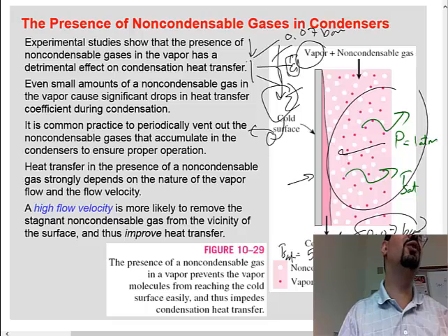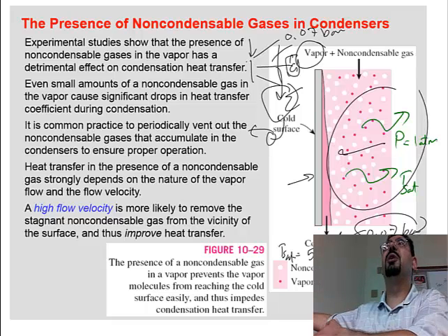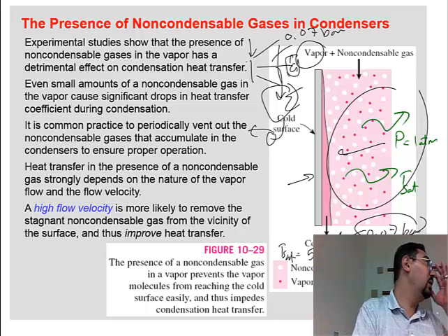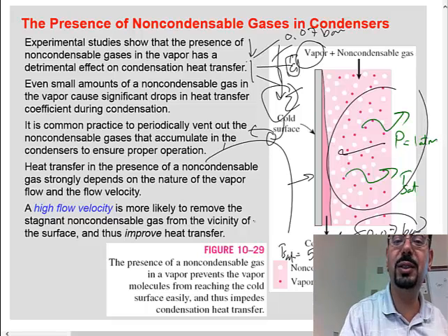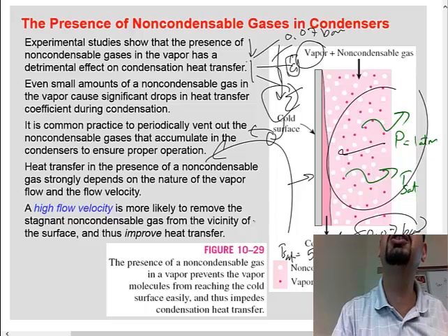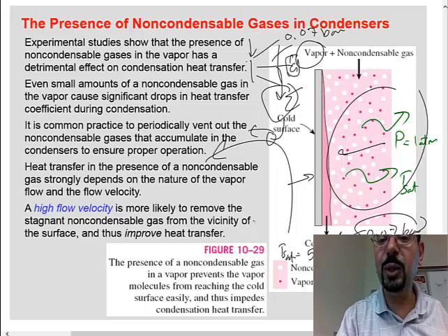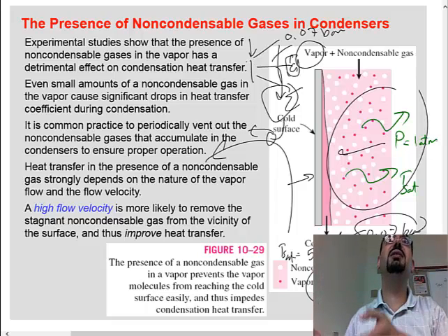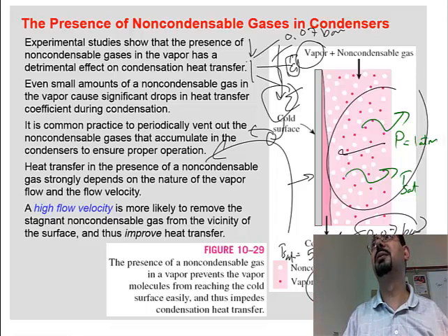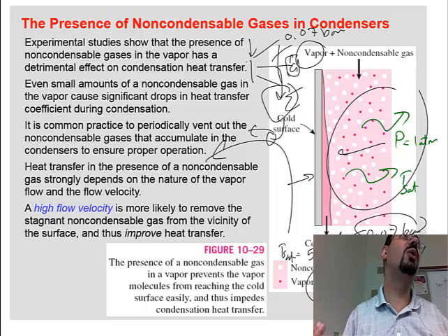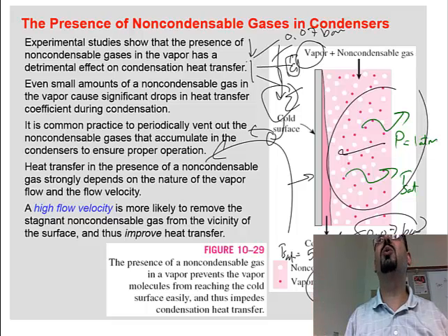What controls the temperature of the wall? The water coming from the river, the Arkansas River for example, into the condenser to cool it, right? That's the cooling water that's cooling the steam. So the water didn't change its temperature. And what happened now? Now the vapor is sitting not at 50, it is sitting at 40. Will it ever condense? Not really, or at least its rate of condensation will drop. Why? Because its T saturation is lower now. Right? And that would require us to cool the water more.